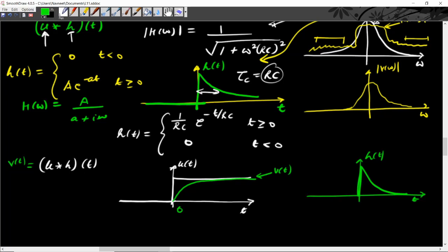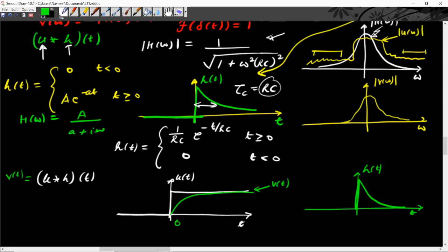Or alternatively, we can think of it as, because we have this step function, the high frequencies required to represent the spectrum of this step function are attenuated, because upon convolution of this step function with this exponentially decaying function, we take the product of the Fourier transform of this step function with the transfer function, and because the transfer function decays for high values of frequencies, the high frequencies are removed, and therefore we end up in a gradual increase in the signal before it levels off to the steady value.